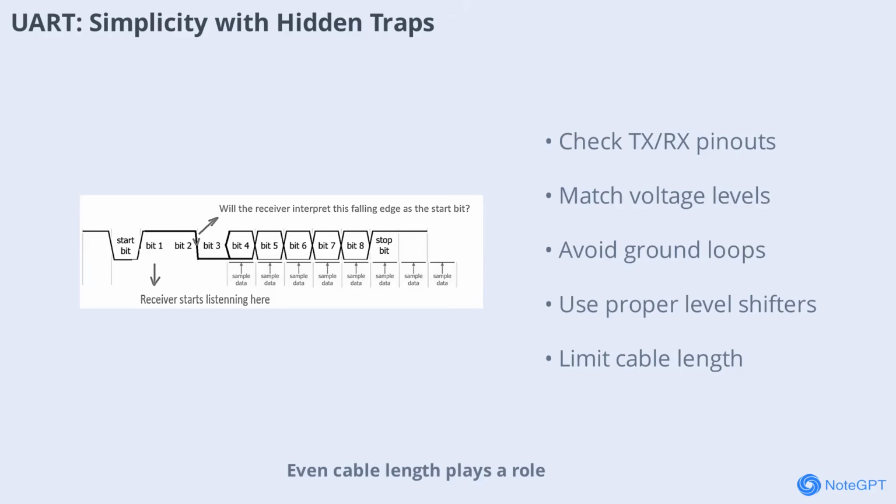Even cable length plays a role. Standard UART signals degrade quickly over distance, so using line drivers or minimizing cable runs is crucial. These are just a few of the many UART-specific issues that can derail a project if not addressed early.